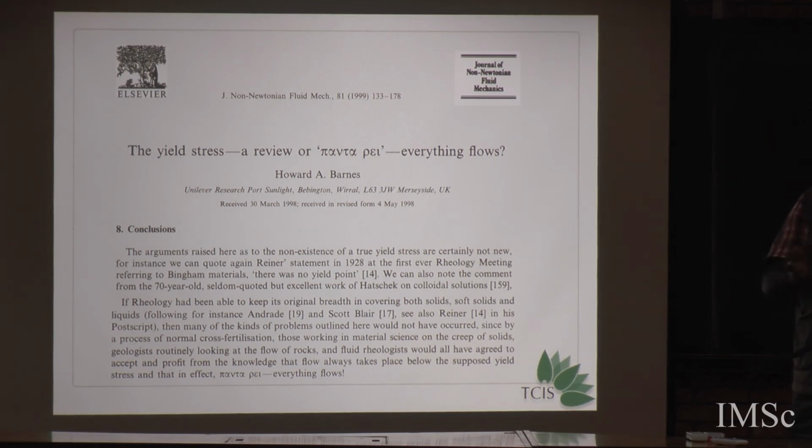However, this variation is logarithmic, exactly the way Takahiro said, that if you decrease the strain rate by an order of magnitude, the yield stress changes by the second decimal place. So people can ignore it, but if you keep plotting how it decreases, it makes an extremely smooth plot, and the yield stress seems to go to 0 as the strain rate goes to 0.